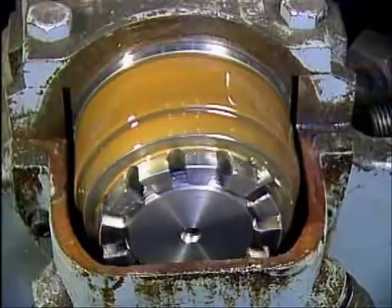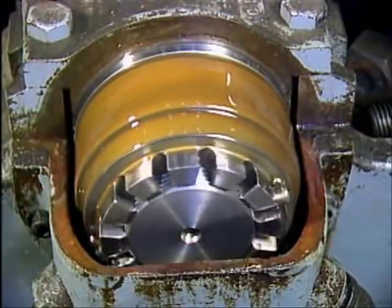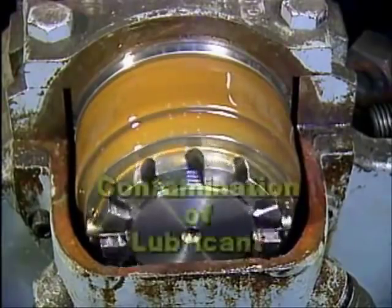Any gear set that begins to show more than light pitting during an inspection should have its alignment checked. And not only should the gear set itself be checked, but the prime mover for the gear set and the equipment being supplied by the gear set should also be checked to make sure that they're not causing the alignment problem. Bearings often fail due to lubrication problems such as contamination of the lubricant.